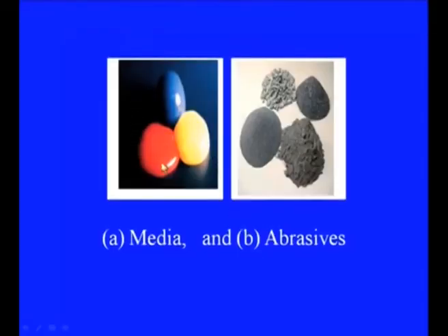Here are some of the carriers, and these are some of the abrasives used in this process. They are mixed together uniformly and that forms the working media. The tooling or fixture in this has the primary function to hold the workpiece in proper position between the two opposite cylinders or in the path of the media.